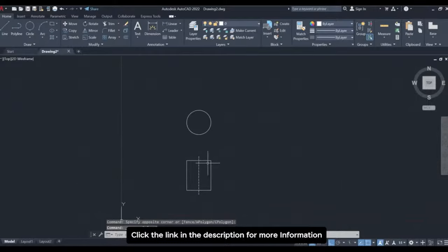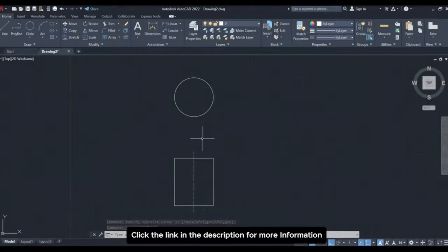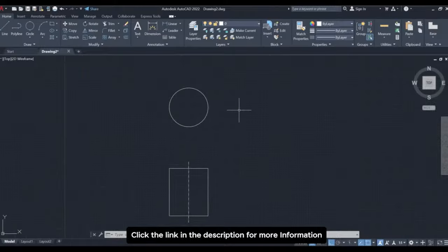Okay. Now, another important tool when it comes to construction geometry is center mark. Now, what are center marks? Center marks are used to indicate the center point of a circle or any symmetrical object like a hole or an arc in engineering drawings. So basically they provide a reference point for positioning and dimensioning, particularly when you're drawing hole patterns, or you want to facilitate some accurate machining, drilling, or milling operation. That time center mark becomes really important.